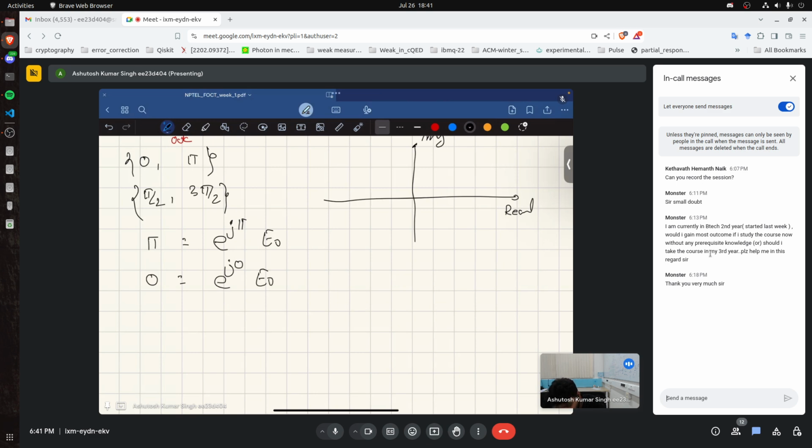You notice the amplitude in this case remains the same. So if I just put a normal photodiode out there, or something that sees the amplitude of the light, it will not register any change. I have to put something that can detect the phase in that case. Professor will talk about phase detectors later in the lecture, but this is what it would look like. This would be your 1 signal, and this would be your, let's call it 0 signal, and then this would be your